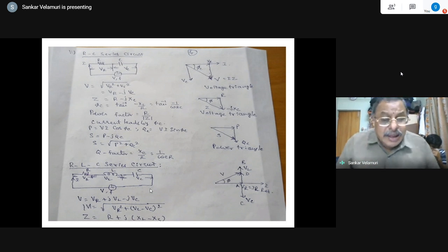So the understanding now is that in series circuits, RL, RC and RLC circuits are generally taken, and you can have a number of components in series also. If you add the corresponding impedances Z1 plus Z2 plus Z3, the circuit may be predominantly inductive or predominantly capacitive, so R plus jXL or R minus jXC ultimately, except the case where Z becomes R, that is resonance, which we will discuss separately.